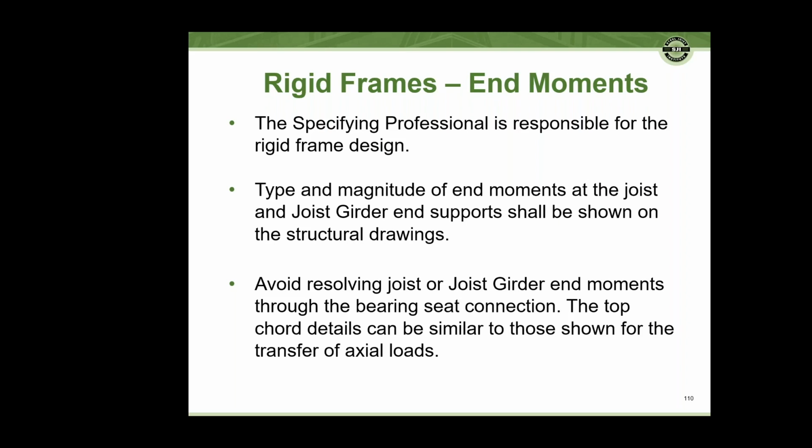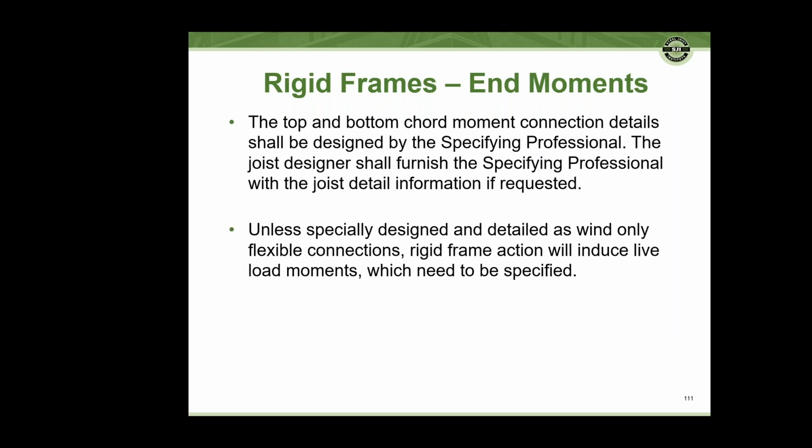The top chord details can be similar to those shown for the transfer of axial loads. And the top and bottom chord moment connection details shall be designed by the specifying professional. The joist designer shall furnish the specifying professional with the joist detail information if requested, unless specifically designed and detailed as when only flexible connections.